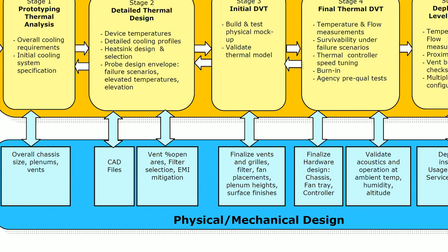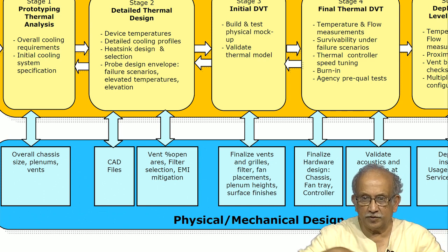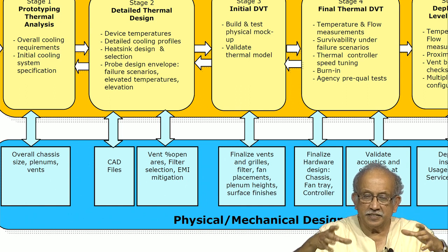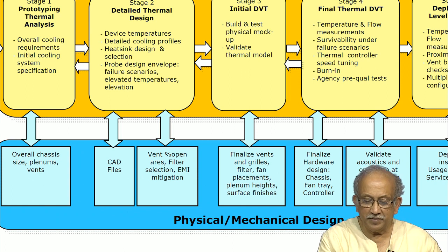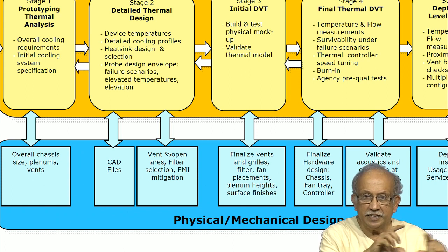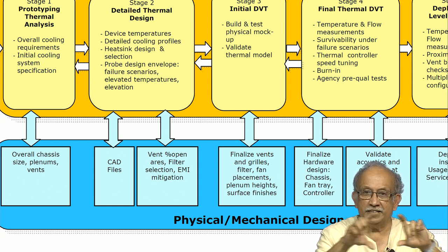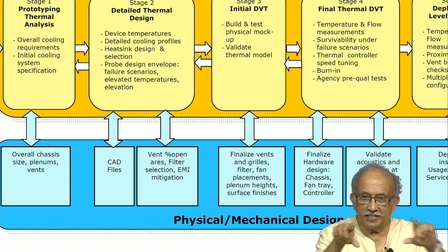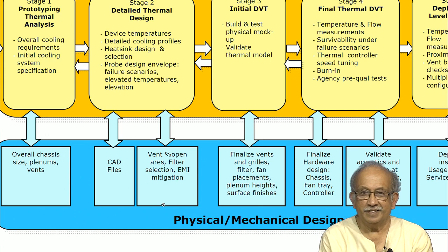This is what I was telling you, percentage of open areas. While the cabinet itself may be big, meaning you have say some 450 mm by 450 mm cross section, the actual spacing for the air to move will barely be about 20%. Again coming back, a vent itself may be about 100 mm high and 400 mm wide, and you usually have some grill on it. So, that is where the filter comes.